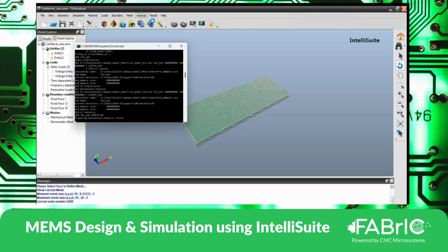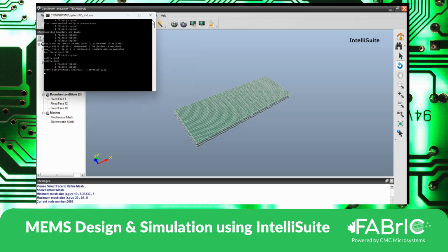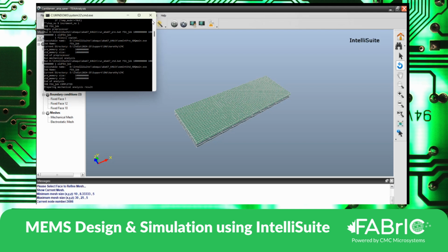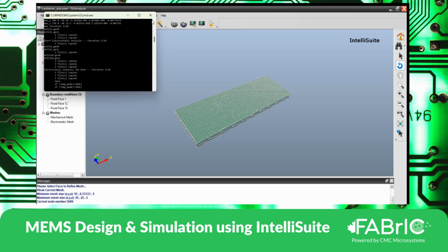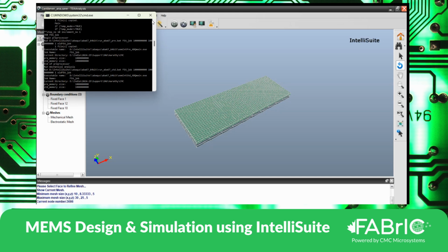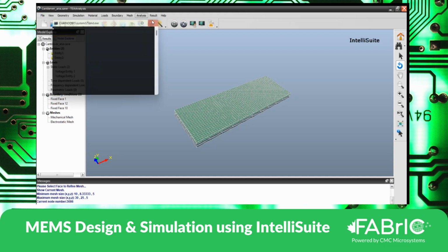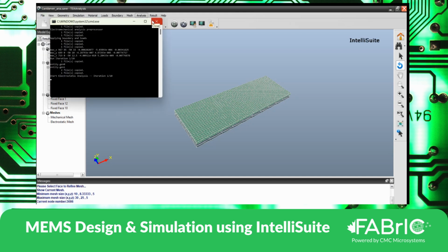So here I would also hint at this: typically electrostatic simulation or electrostatic force-based mechanical simulations are generally recommended to perform a hysteresis-based simulation because of the metal-metal contact, the stiction issue, or it can be deformation due to the electrostatic force.